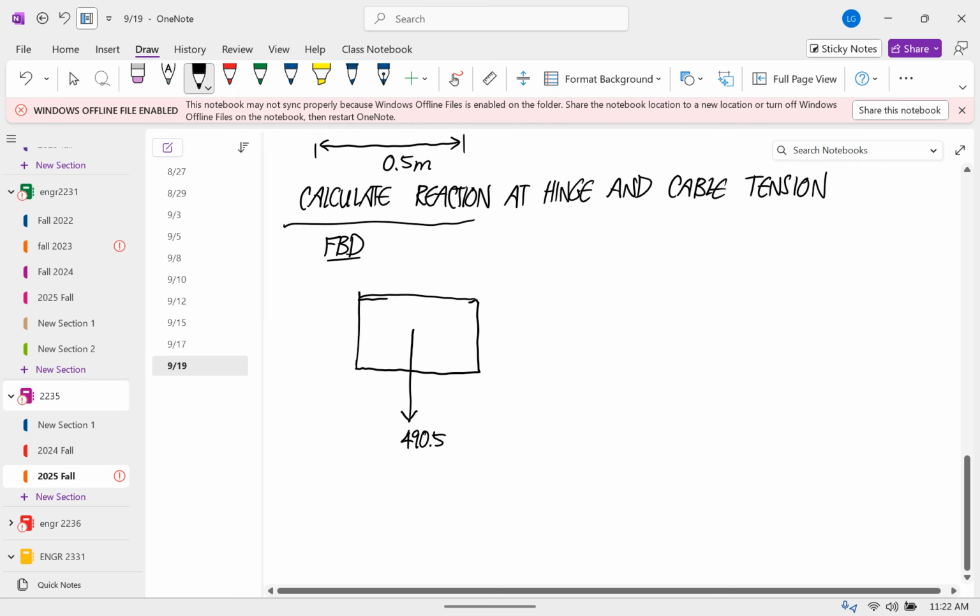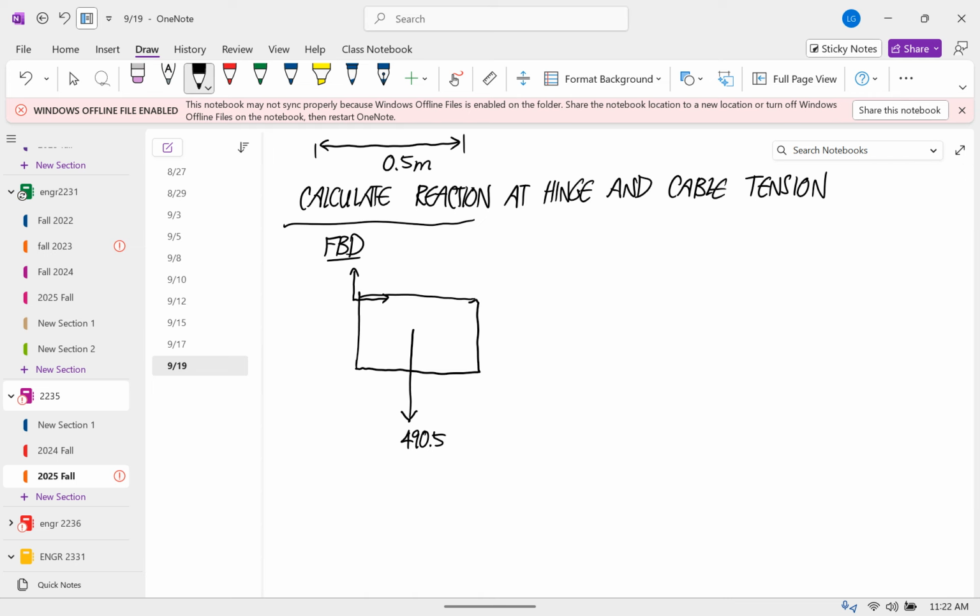So this is an unknown force vector. I could call this the force on the plate by the wall or something, but that subscript notation is only useful if then you're going to later isolate the other thing, and we're never going to isolate the wall, so I'm just going to call this R. All it is is an unknown force vector. And then we have the cable force, and the rules for a cable force are parallel to the cable, away from the body.